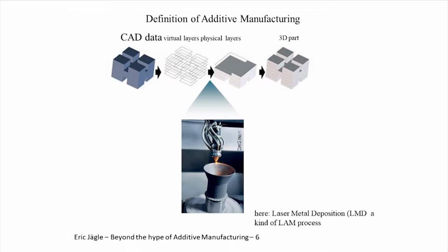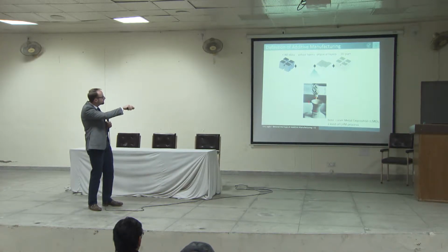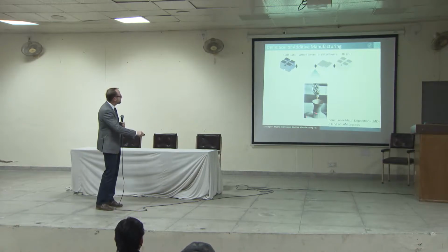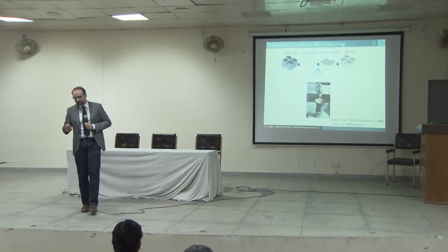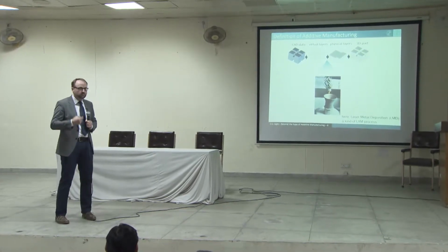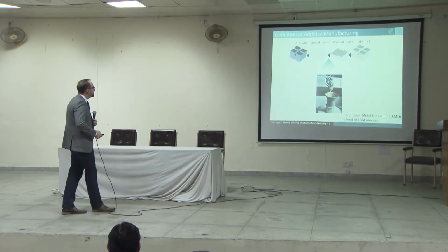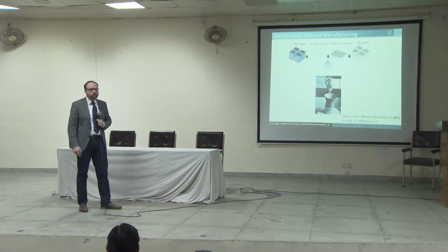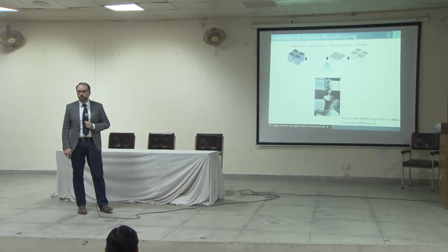Coaxially there's metal powder being blown into the melt pool that is generated by the laser, and you rotate this structure here in the bottom, and therefore slowly you build up this conical structure here. All right, but even though of course I'm a metal specialist, as you can tell from my affiliation, these kind of processes where you can work with metals are by far not the only additive manufacturing processes.